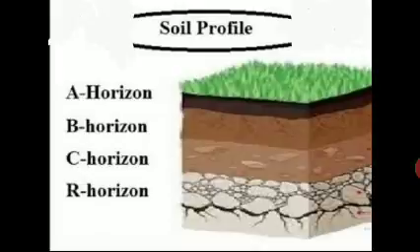For soil type light, the percentage of clay present is 2 to 10, and it is suitable for crops with less water requirement for irrigation. For normal or medium type of soil, the clay percentage will be 10 to 20%, and the water requirement is ordinary. For heavy soil type, the clay percentage is more, that is 40 and above. A large quantity of water at regular intervals is required.